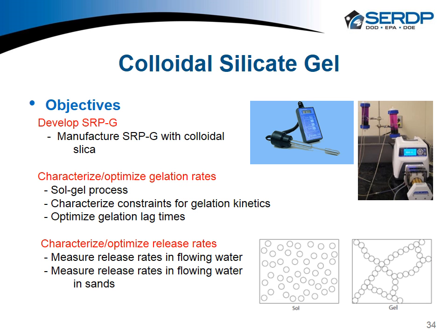Here, lag time means how long this mixture of colloidal silica and dense permanganate solution can flow after the injection without being gelated, so that it can spread away from the injection wells for a while, and then gelate to become gel. So that time is what we call lag time. We wanted to make lag times longer or shorter, and we wanted to find a way to control those lag times as well.